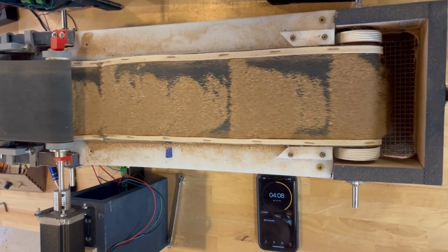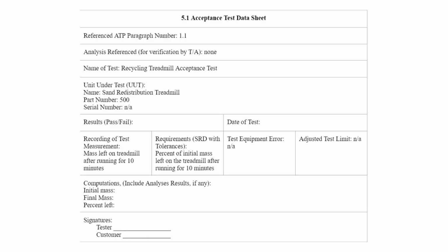Another improvement to the SRT was changing the conveyor belt material to material that is less stretchy and more textured. This helped keep the conveyor belt on the rollers, where before we had trouble with the conveyor belt walking off to the side of the roller.